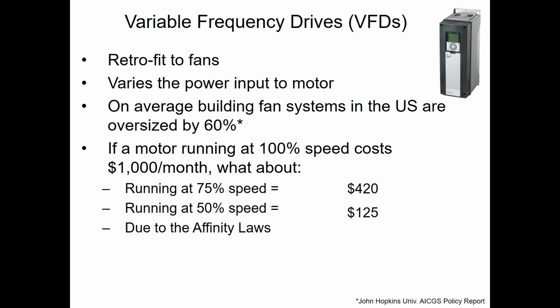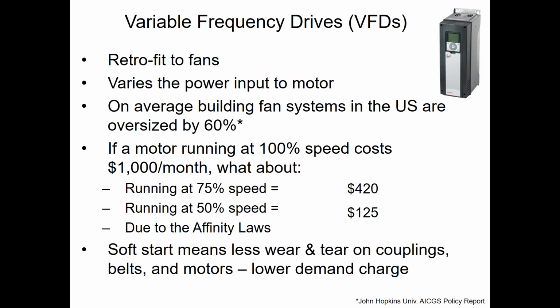And we'll explain the affinity laws that apply to our situation here in a minute. We'll talk about why it works. In addition to the energy savings and getting us the airflow we need and quieter sound when it throttles back, the other benefit of having a VFD on my fan is that it means less wear and tear.